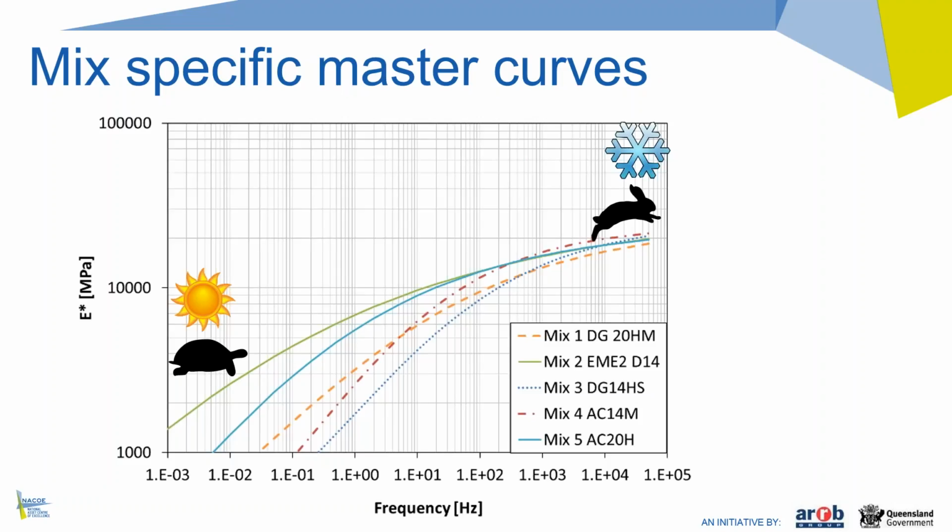If you look at the bottom left of this slide, you will see that at 1000 MPa the line is drawn. That's because currently the minimum modulus that we use in mixed pavement design for asphalt is 1000 MPa, and we're not proposing to change that. If you do testing in the laboratory, you will get values below 1000 MPa. I hope that answers the question.